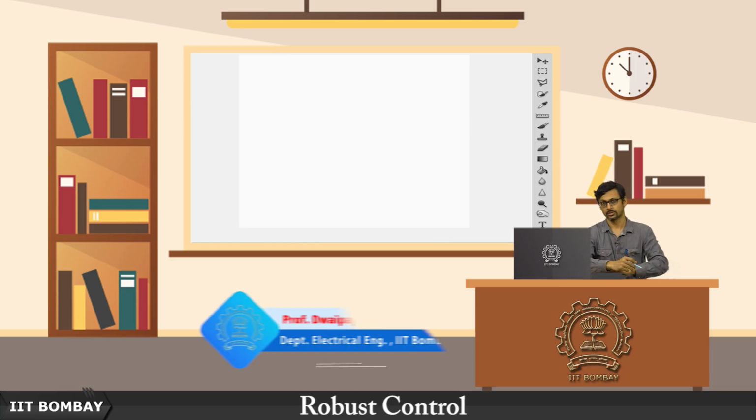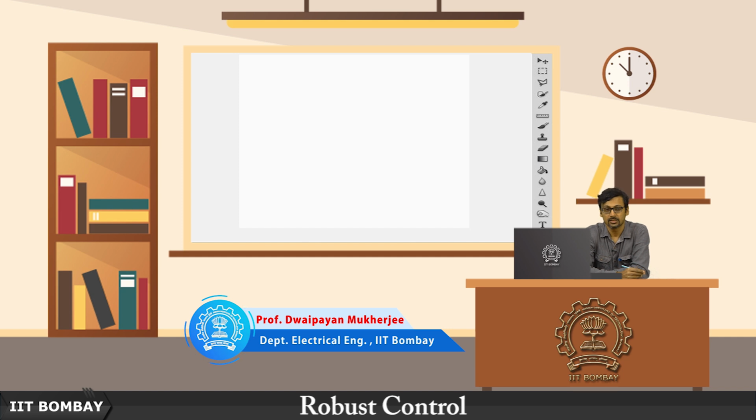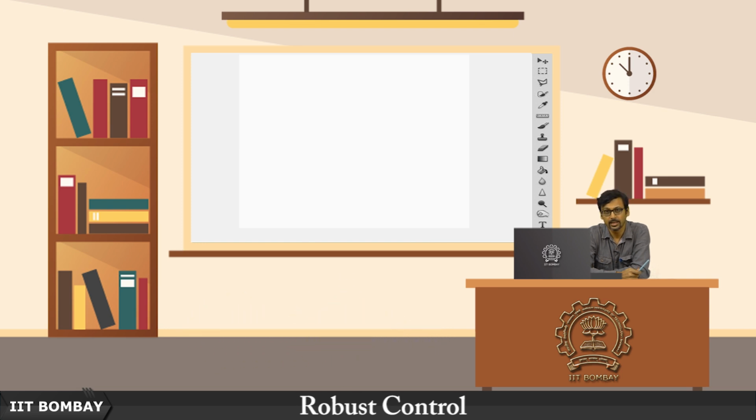Welcome back to another lecture of robust control. So over the past few lectures, we've been analyzing, or trying to get a handle over, this H2 optimal control problem, the synthesis of the H2 optimal controller. Contrary to conventional approaches which approach it from the optimal control perspective, we've tried to give you an algebraic flavor for the problem. In today's lecture, that same approach will be bolstered even further when we'll not just look at this Riccati equation based approach that involves these Hamiltonians, but we'll also give you an LMI formulation of the same problem and a way of solving this problem using LMIs.